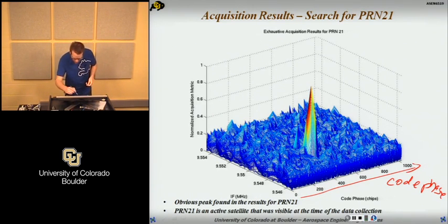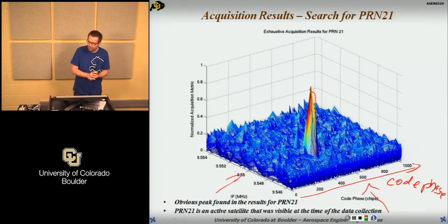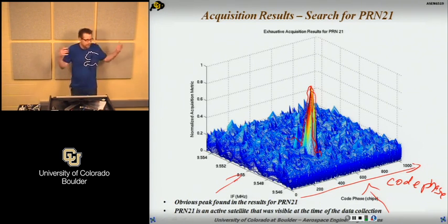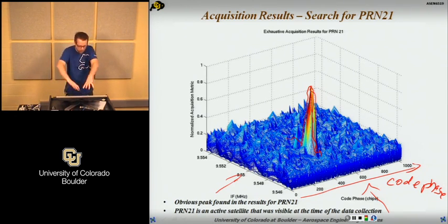And here, if we squint a little bit, we can see that it looks like a triangle in this space, if we look from this side. From this side, it seems wider in some cases. What we actually have here is something called the sinc function. You can't really validate that from this picture, but trust me, it's a sinc function. And it was all noise before. We found the correct code phase and carrier frequency, and we brought the signal up above the noise floor, right? You have a clear peak. If you look at this, I would say, without a doubt, we got a signal here.